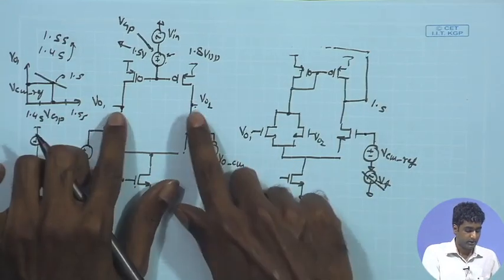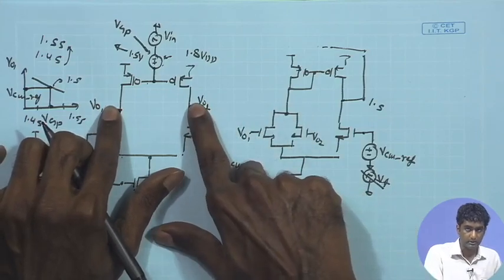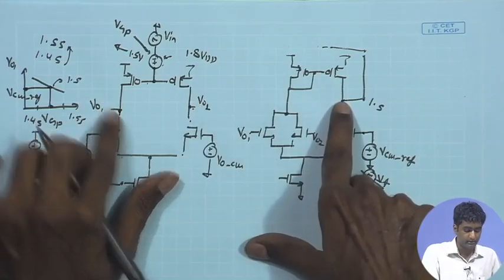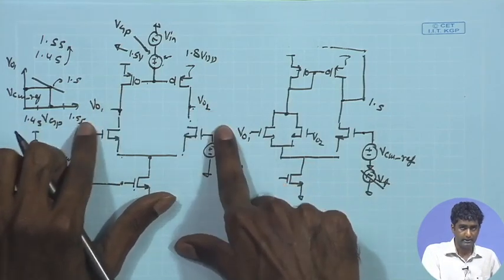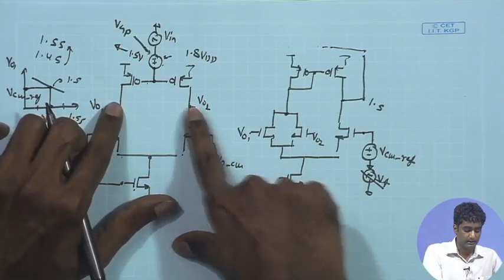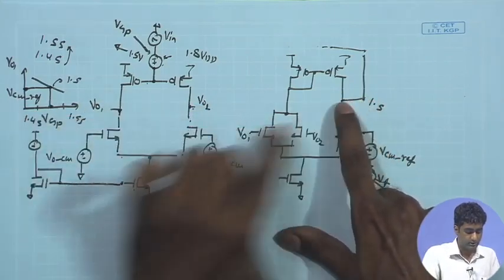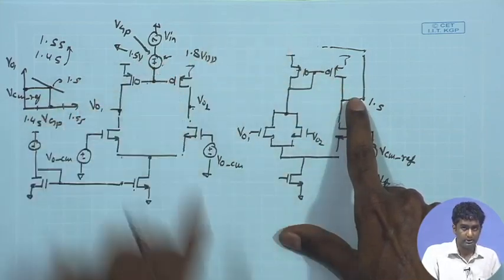And if we look at the overall capacitance, suppose you are putting the capacitance between this point and this point, then of course the main amplifier also has the Miller effect, and the overall capacitance over here will be multiplied, whereas for the other node, when you are putting the capacitance, that effect is not coming into the picture.